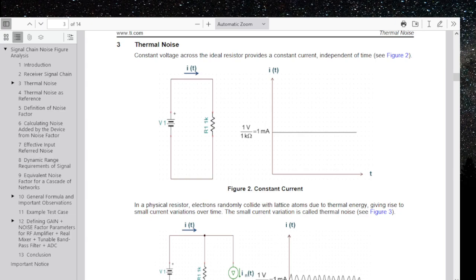And this would have to be down into the millivolts range. That can be done. And I want to set up a Wheatstone bridge circuit. I've got a huge wire wound resistor that's a certain value, like 30K. We're going to set that up with a Wheatstone bridge with another resistor that's 30K to balance the circuit, but there's going to be imbalances, because you got to match impedance. So we're going to have an impedance Wheatstone bridge that is perfectly balanced, and we're going to use the large resistor as an antenna to pick up noise in certain areas.